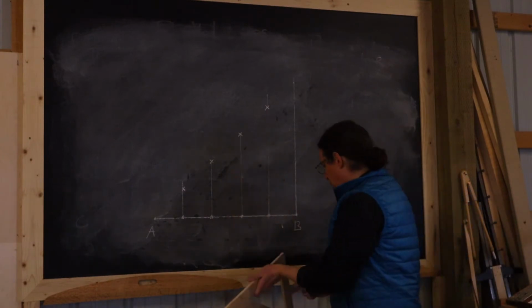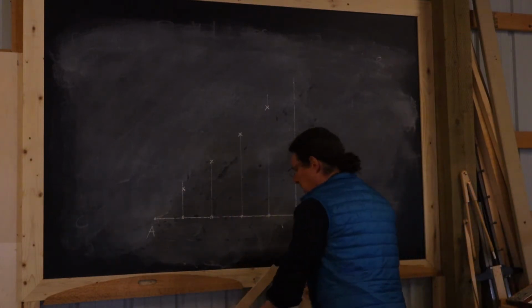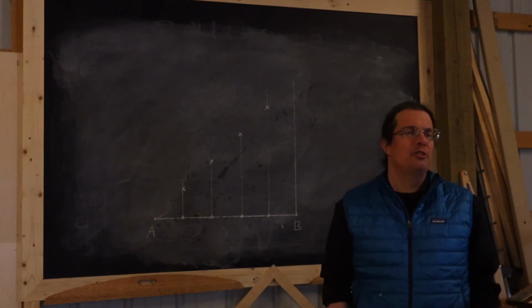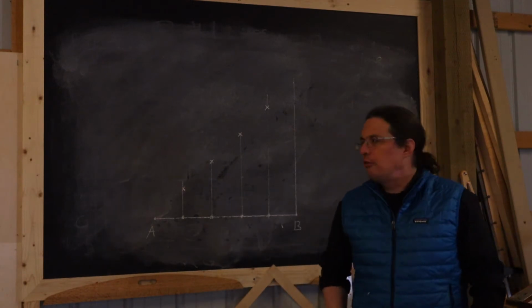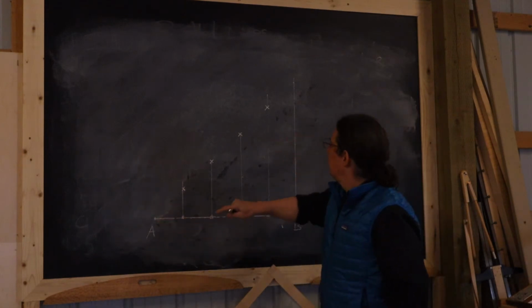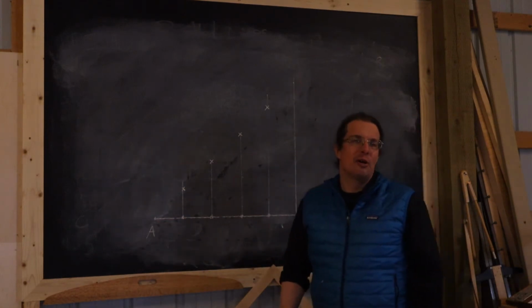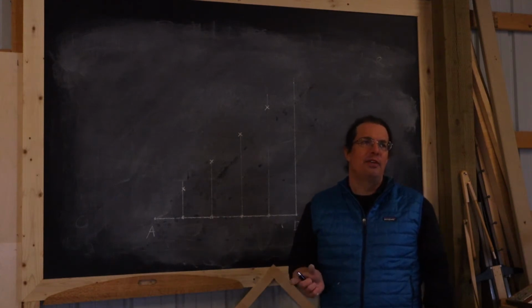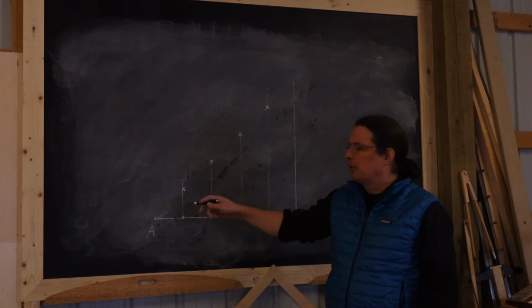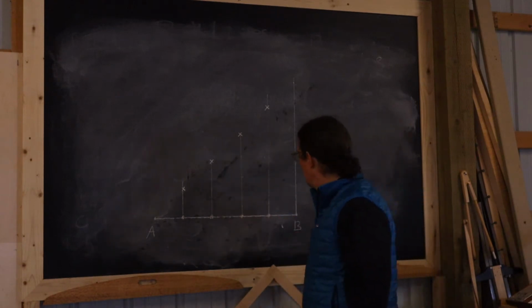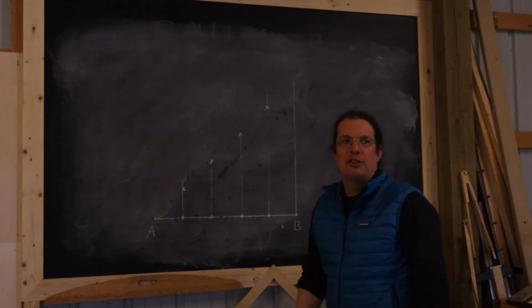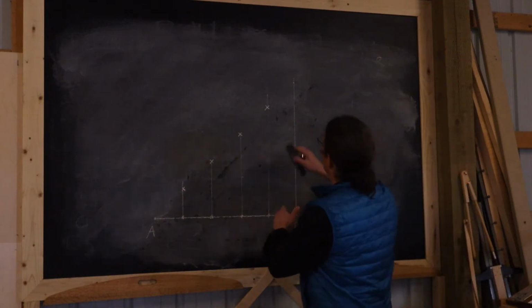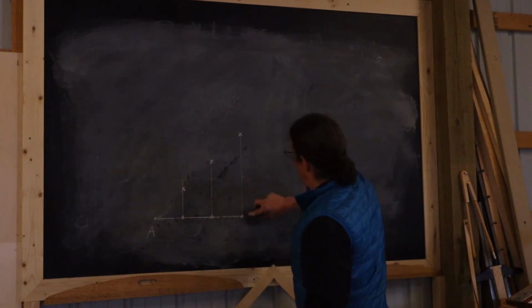And so if I wanted to do some other number than 5 segments, maybe I wanted to do 7 segments, in that case I could have still had the 0 mark on my ruler here and the 35 mark on the ruler up there, except that time 1/7 of 35 is 5 inches, and so I would have marched along in 5 even steps. Right, so that's a way to divide a segment into a given number of equal parts. There's one other technique.